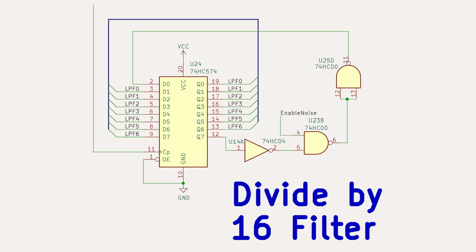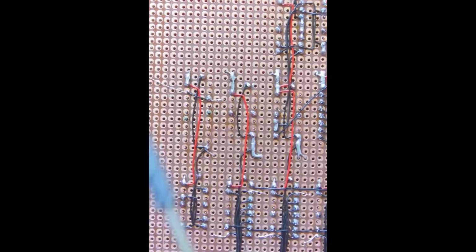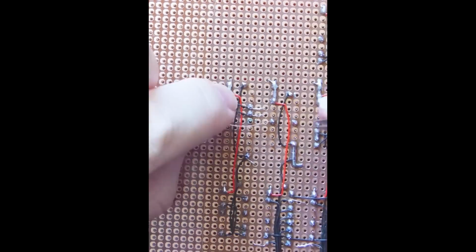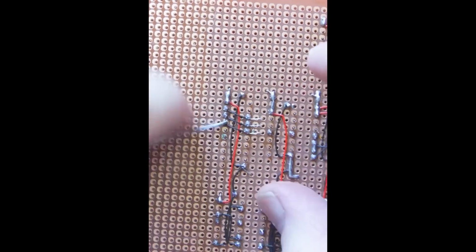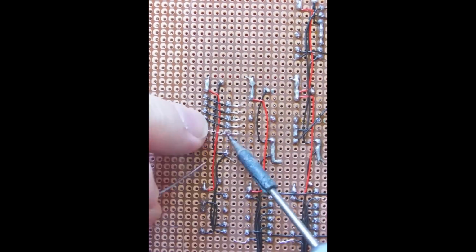I'm going to use a regular 74HC574 octal D-type flip-flop chip instead of the shift register chip. I'm wiring up the output filter. I'm starting to get a bit low on real estate on the board. I figure I've still got space for 5, maybe 10 chips if I can push it, and I'm going to use that for generating the logic to handle the different screen resolutions, which really is the last challenge.